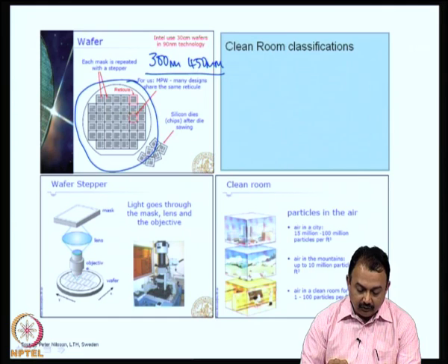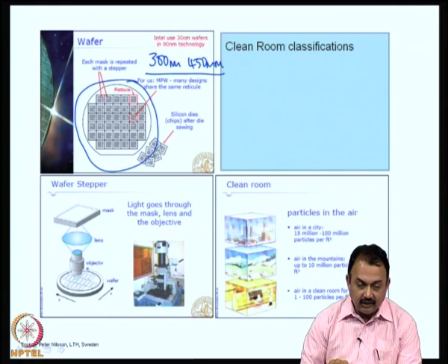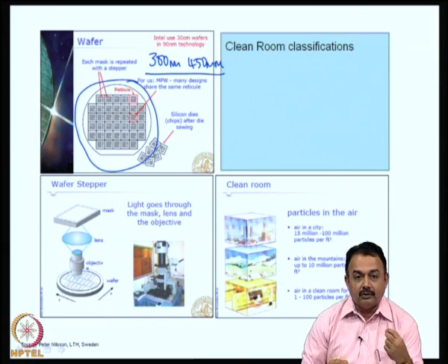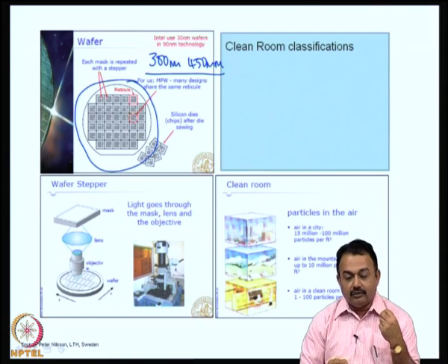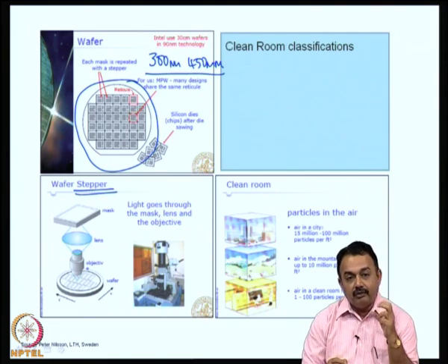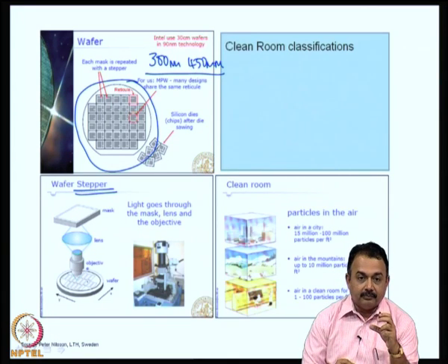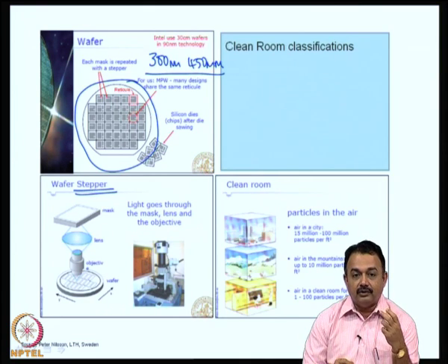Now, normally when you use a photolithographic process, the image is sometimes twice, 4 times or 6 times more than the actual size of the die. So, basically a stepper process is used to reduce the image that is falling onto the wafer. In that way, a good collimation is done and a good resolution can be established instead of using a direct 1:1 image.